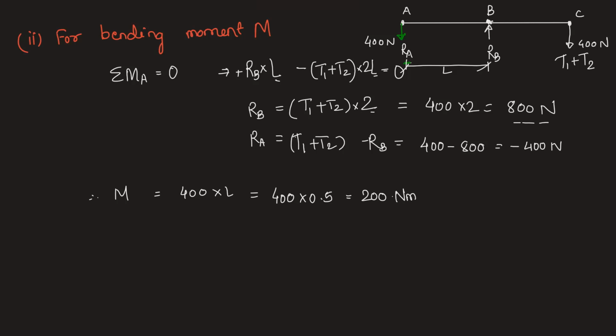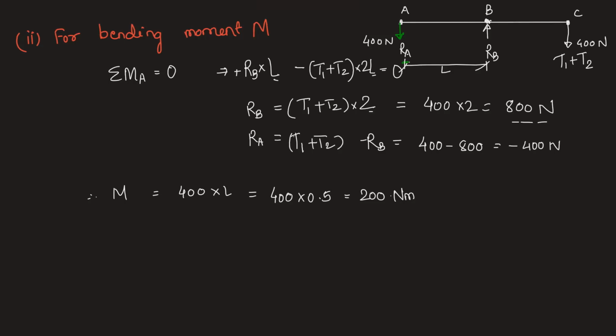So let's write the first equation that we have written. As mentioned, according to the shear stress theory, the maximum shear stress in the shaft AC should be less than or equal to the given shear strength value for the material. So we can use the limiting condition, which is tau max is equal to tau s, to solve the question, that is to find out the value of T. Therefore, we can write down, according to shear stress theory, tau max is given as 16 by pi d cube under root of bending moment square plus torque square, as we have written earlier.